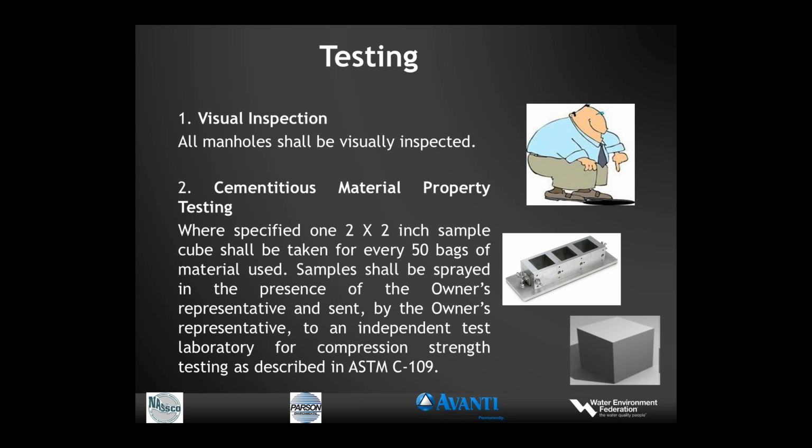So it's not acceptable to be standing up on the surface with sunlight glaring at you and look down into a manhole and expect to be able to visually verify that the manhole has been improved properly. So visual inspection really does require an inspection from inside the manhole.